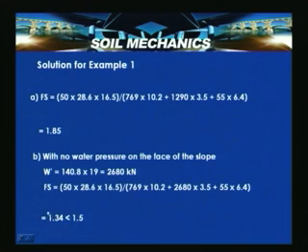Substituting here we get a factor of safety which is less than 1.35. So, the presence of water, if it exists on both sides, increases the safety. But if there are fluctuations in the water table, that means sudden drawdown conditions, these can affect the factor of safety.